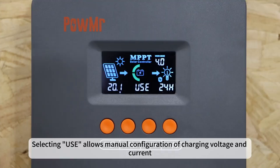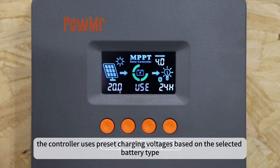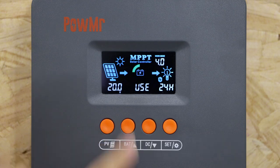Selecting USB allows manual configuration of charging voltage and current. For other specific battery types, the controller uses preset charging voltage based on the selected battery type. We will now enter menu settings to demonstrate how to customize the charging parameters.